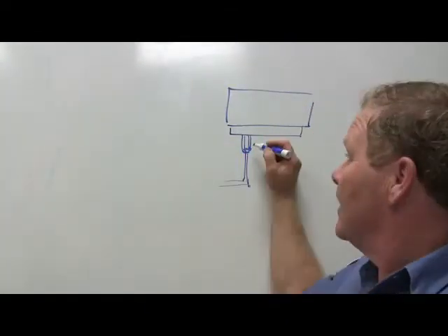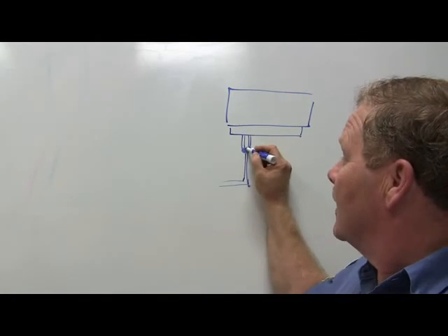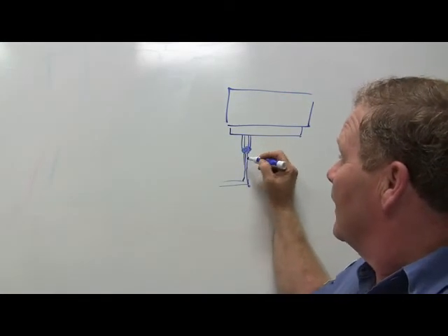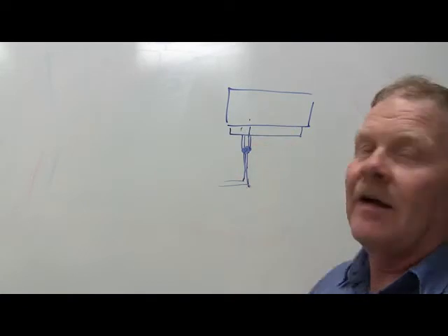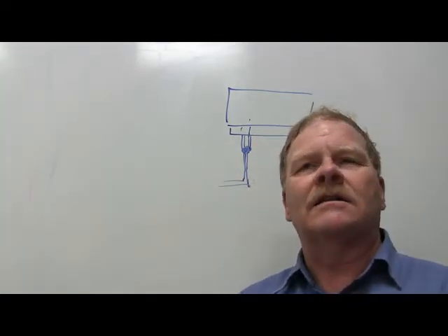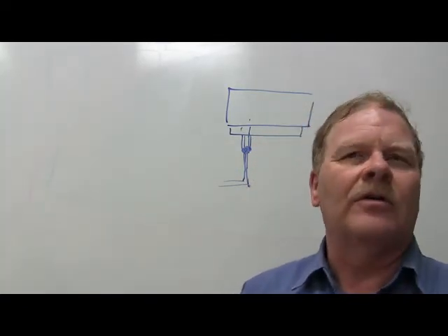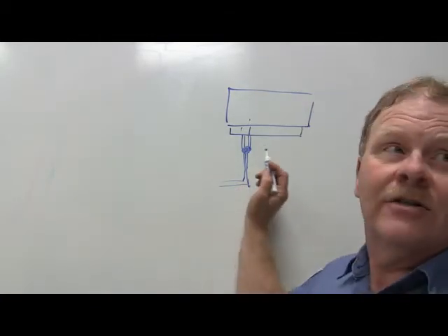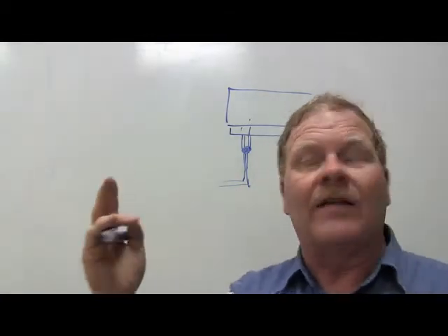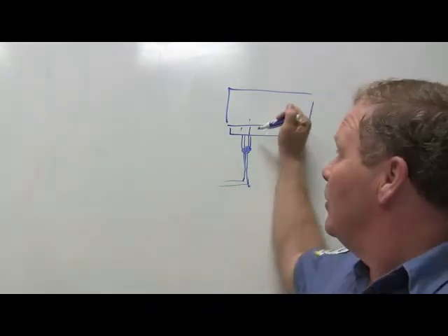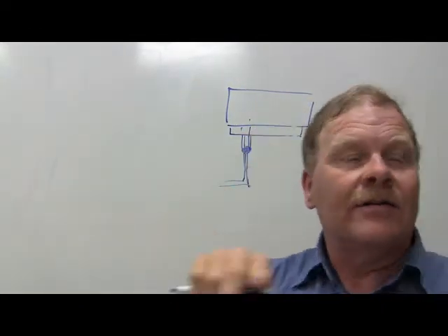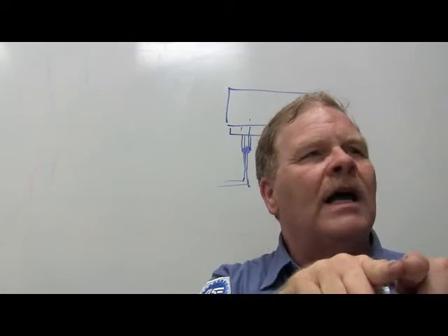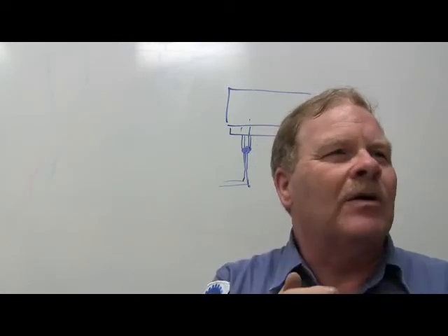They'll actually be connected right here, coming out of this controller off that board. The reason they do that is because they're trying to pull something like a fan motor that's heavy and hard to pull. They want to make sure there's enough current able to flow out of that circuit board, so they have two connections to carry that load. If you've just got one, it'll start to heat up and burn things up.